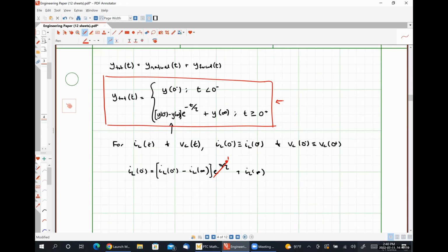Now, if you have trouble identifying whether or not the independent sources are connected or disconnected, you can just use this expression right here. The only thing that's going to do is you'll do a little extra work proving that things are settling to 0 at t equals infinity. All the other steps are just the same. So let's work an example.